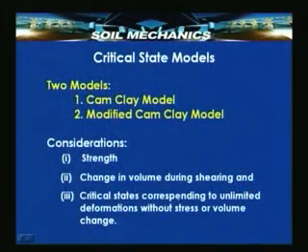The basic considerations in development of these models were what is the strength of the soil, the change in volume that takes place during shear, then what are those critical states corresponding to large deformations without stress change or volume change. If you think of liquefaction, it is very easy to comprehend the meaning of this statement. Liquefaction is nothing but a case of large deformation at constant stress or constant volume, and therefore, the Cam-Clay model attempts to explain these large deformations which may take place under constant stress or constant volume conditions.